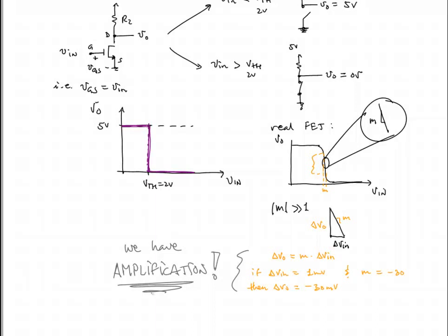That's what is needed even for an inverter here. We want, in a small change or range of input voltage changes, the output to slew from being high, like 5 volts, down to something low, like 0 volts. Furthermore, we're going to find that the transistor is useful for a whole lot more than just a digital inverter.